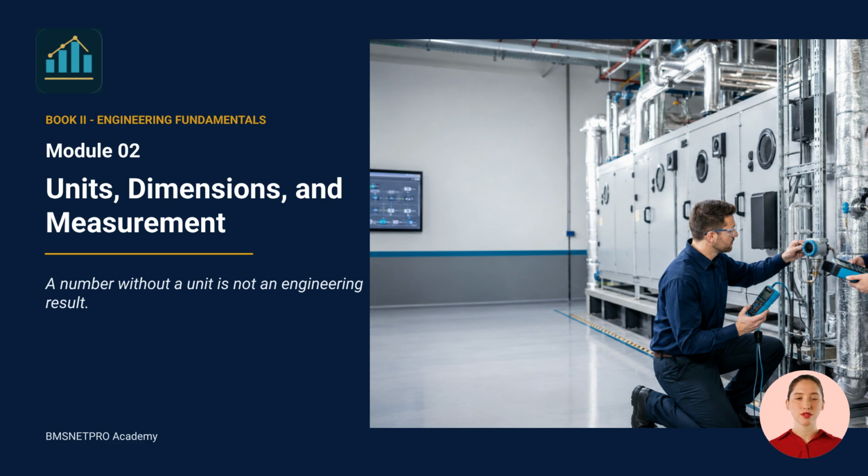Welcome to Module 2, Units, Dimensions, and Measurement. In building automation, every point, trend, calculation, and control decision depends on measurement. A value like 25 is meaningless until we know whether it is 25 degrees Fahrenheit, 25% relative humidity, 25 psi, or 25 kilowatts. This module teaches learners to protect engineering decisions by preserving units, understanding measurement quality, and checking whether BAS data is fit for the decision being made.